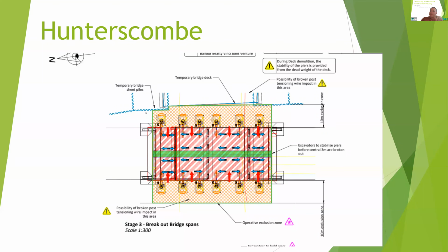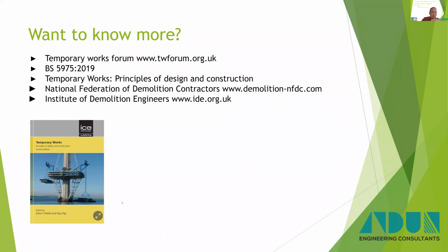So that meant there was a residual hazard there. Now, given the fact that the anchorages were well above the height of the machines, and the machines were demolition spec, it was risk assessed and it was deemed acceptable to use demolition spec machines with an exclusion zone in place to allow the demolition to be completed. And nobody even spotted this non-grouted tendon during the works. So that one's completed successfully as well.